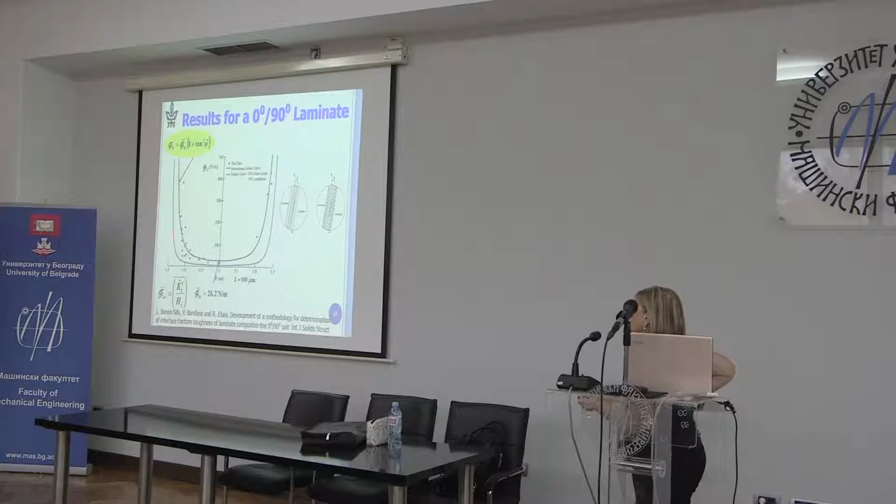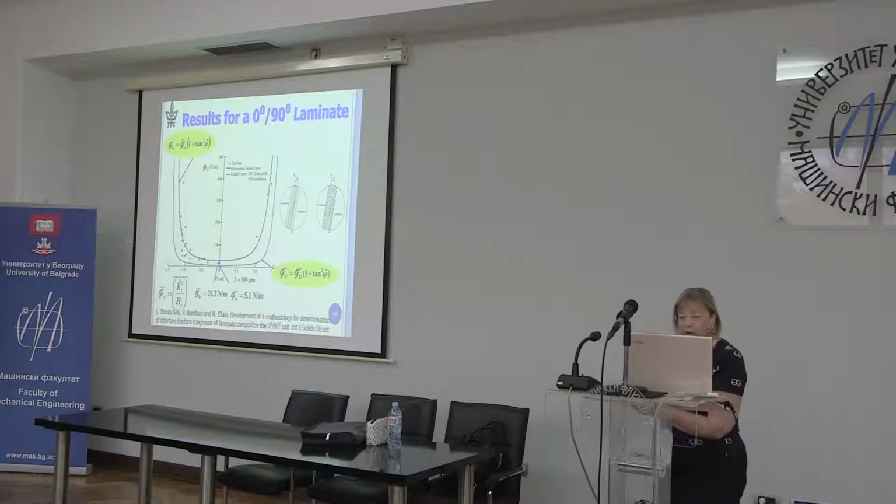Anyway, we don't like these points below, and we use two types of specimen, and the scatter from these specimens is sitting in the scatter from the other specimens, so we felt we really do have a fracture criteria. We really do have critical properties. This is the curve for which any next test or structure that you calculate will only have a 10% probability of failure below this curve. All the points went above this statistically obtained curve, but of course it's a big payment. We went from 26 to 5 newtons per meter, and that's a very big payment.